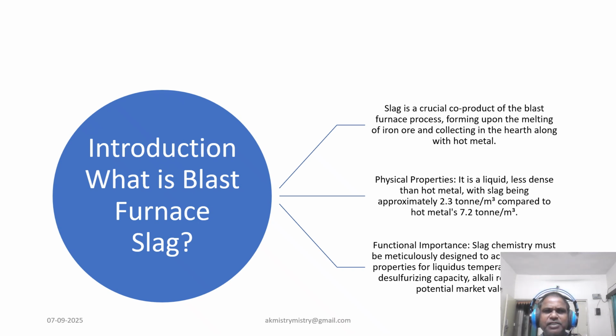The quality of this ferrous burden is paramount. While beneficiation at the mine aims to reduce gangue, some is actually necessary. For example, for proper sinter quality, operators would not typically go below 3.5% silica in their sinter, with 4.5 to 5.5% being more common. A mere 1% increase in silica in the burden can increase slag volume by 40 to 50 kg per ton of hot metal, showcasing the significant impact of this initial input.